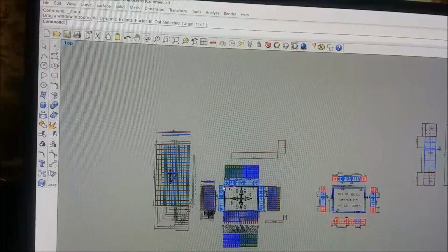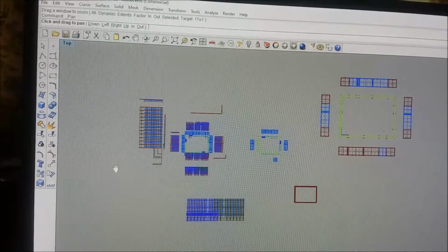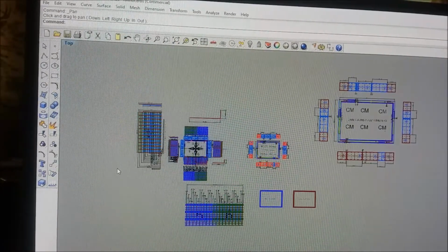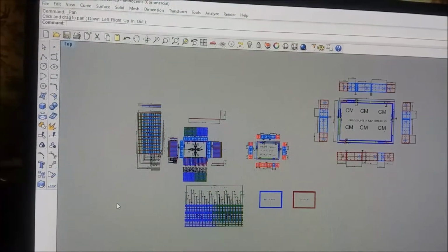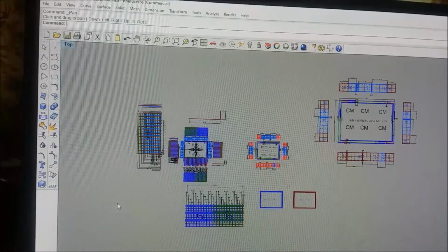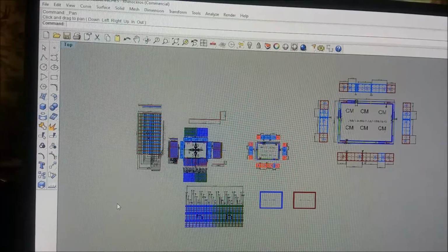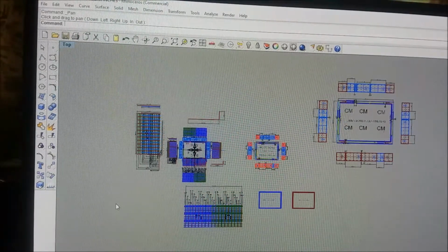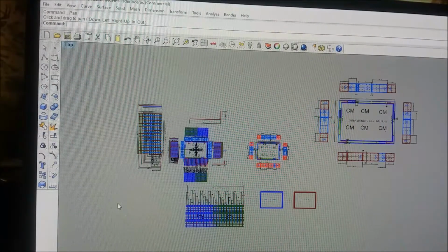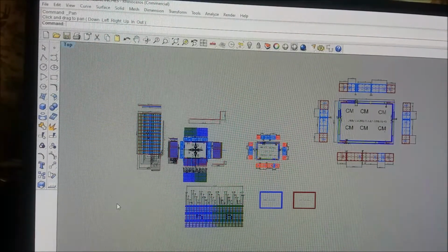And the beginning of this and the other 2 videos in this group, it just shows you how many you're supposed to have. If you're having a house built and it looks like you're really light on rebar, like if you see number 9 or number 10 rebars, 40 centimeters on center, laying on the ground, not even supported, you might want to talk to your builder. Better to upset him than have a faulty house collapse on you.